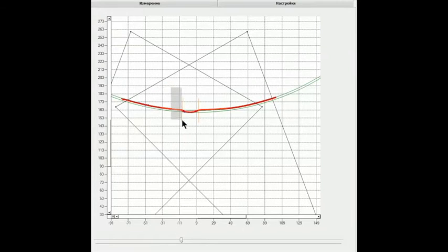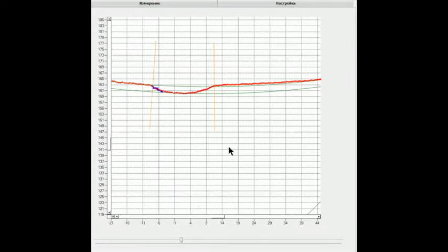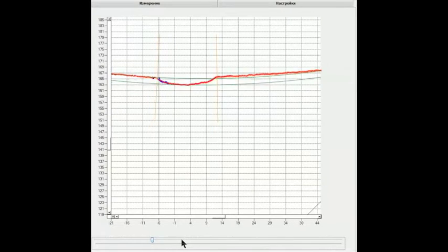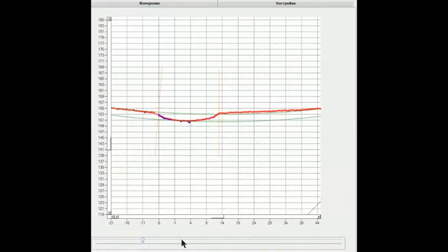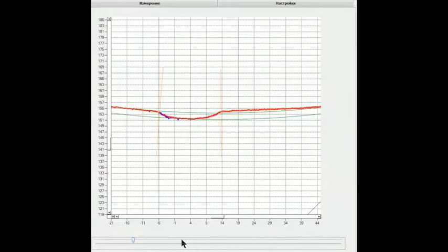The measurements are made continuously at pipe movement with a step of about 5 mm. The fluctuation of these measurements, which we see on the screen, corresponds to the pipe passing through the roller track and is connected with the pipe displacement. At the measurement the weld profile is clearly seen, even if the pipe is moving. All the captured parameters are shown on the screen.